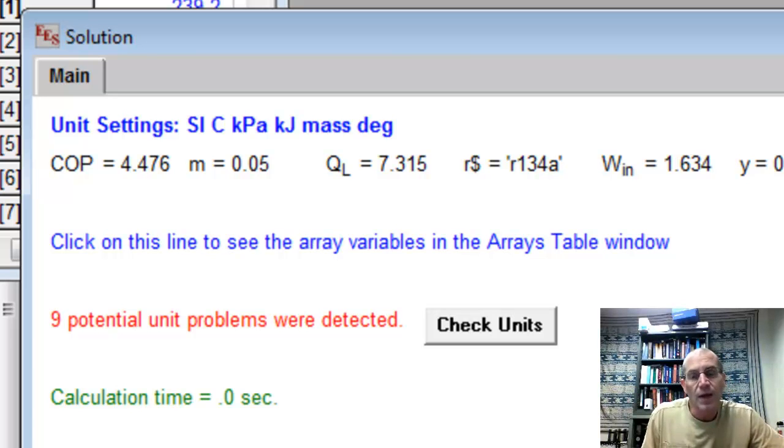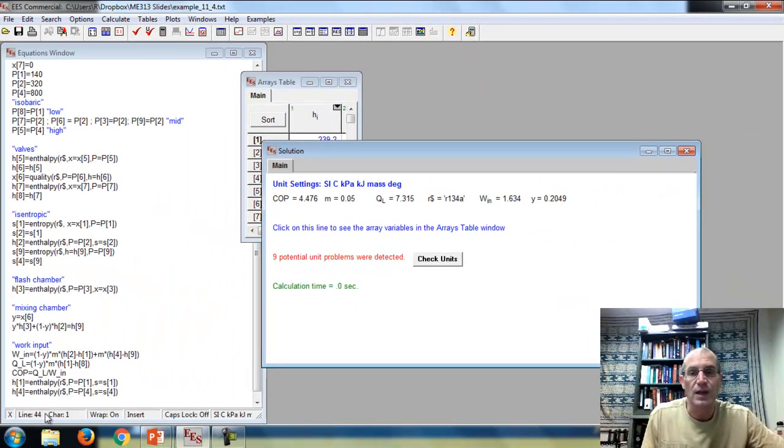work input. And so the determination about which one you want to use is going to be what the particular temperatures are that you're operating at, what the desired use of that refrigerator is, and maybe what the component costs are. They both require two compressors, but those compressors are going to be running at different mass flow rates. So it kind of gets down into an engineering calculations and economics problem to determine which of the two you would prefer to use.